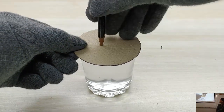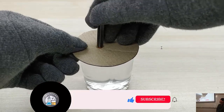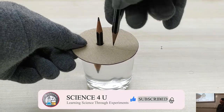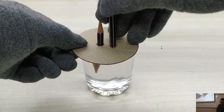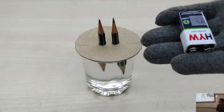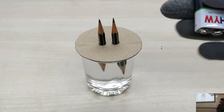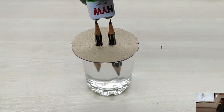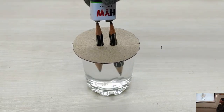So graphite's not a metal, but it has excellent electrical conductivity in 2 dimensions. But the way graphite is, it has a whole bunch of little crystals sintered together, and therefore it can conduct in 3 dimensions. And so they're using graphite electrodes rather than the stainless steel electrodes on the battery.